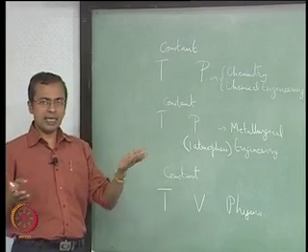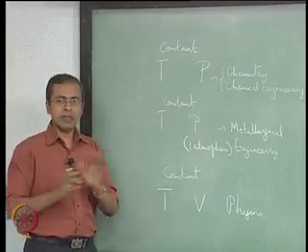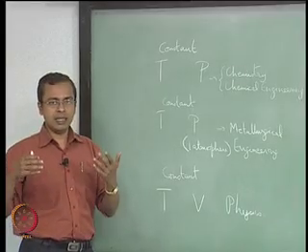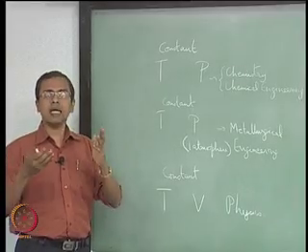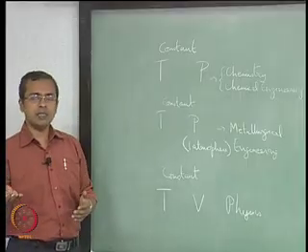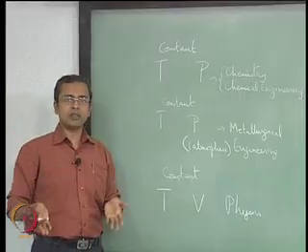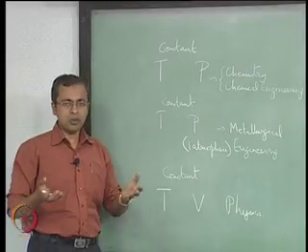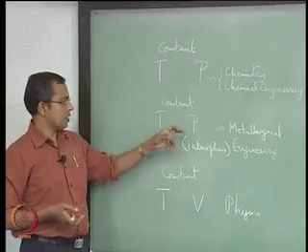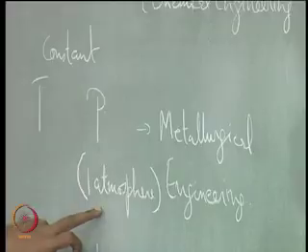Okay. You can generate at other conditions also, but typically you will see temperature versus composition, and the assumption is that, or it will be stated somewhere of course, that the diagram has been made at 1 atmosphere. Okay. So, you could have done it at some other pressure if you had wanted to, but in general it is going to be done at 1 atmosphere. So, a large amount of the database that you will come across in metallurgical engineering will be constant temperature, constant pressure, with the pressure being 1 atmosphere.